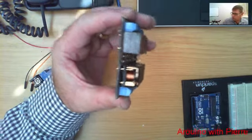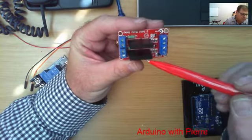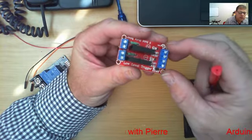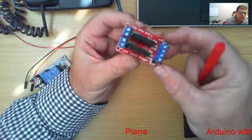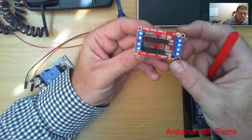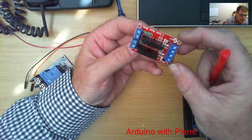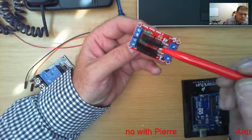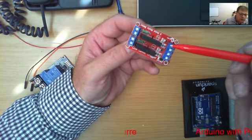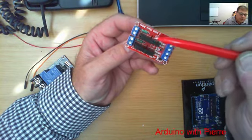Now if we move towards a solid state relay, they look like this. And this is a solid state relay. It does not contain any physical contacts, so obviously it will last much longer because there's no mechanical movement in that. You can also switch relays like this quicker. And another advantage of them is you need a smaller current to basically activate that switch.